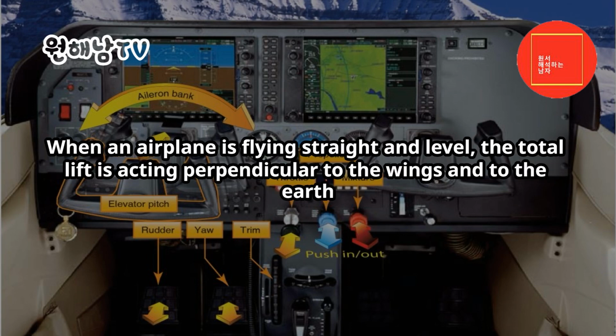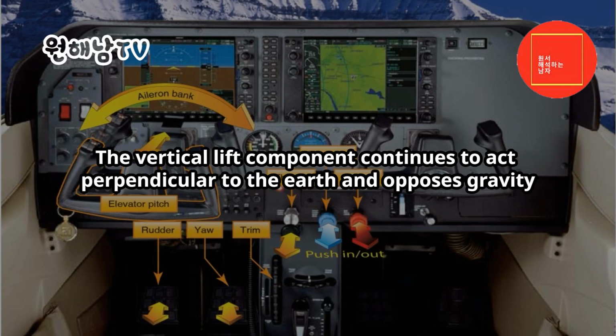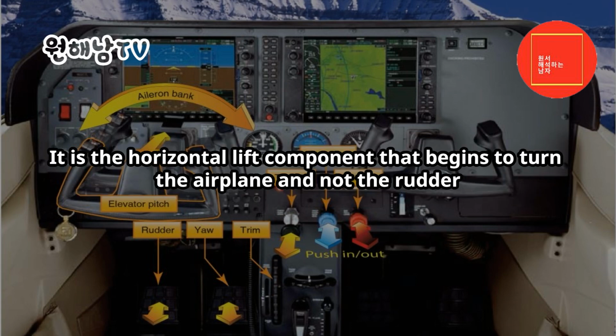When an airplane is flying straight and level, the total lift is acting perpendicular to the wings and to the earth. As the airplane is banked into a turn, total lift is the resultant of two components, vertical and horizontal. The vertical lift component continues to act perpendicular to the earth and opposes gravity. The horizontal lift component acts parallel to the Earth's surface, opposing centrifugal force. These two lift components act at right angles to each other, causing the resultant total lifting force to act perpendicular to the banked wing of the airplane. It is the horizontal lift component that begins to turn the airplane and not the rudder.